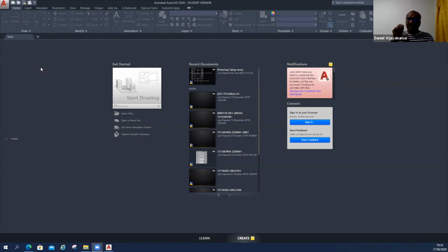Beginning means when you set the drawing size, the drawing paper, in your AutoCAD application. For example, first we choose the limits, right? Then the zoom command. The third one, we start the line command, but the third should be setting this dimension style manager.